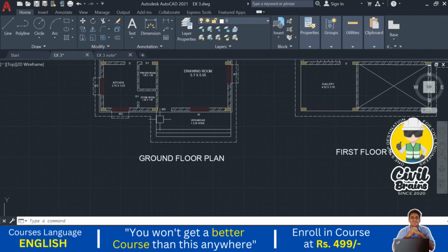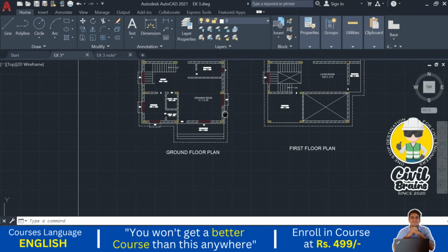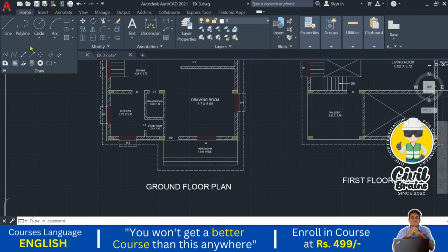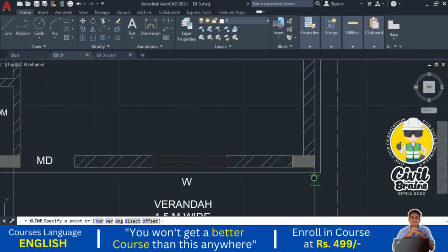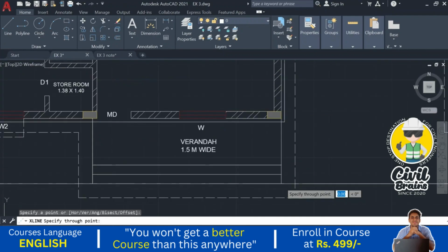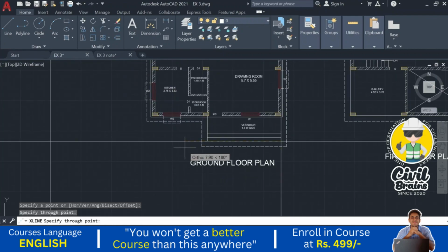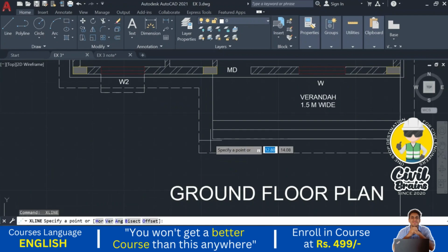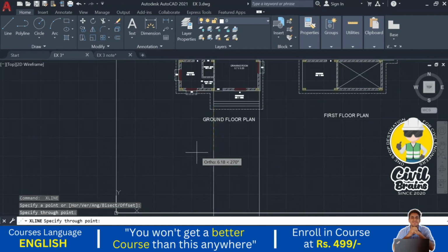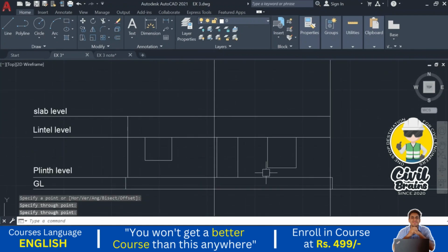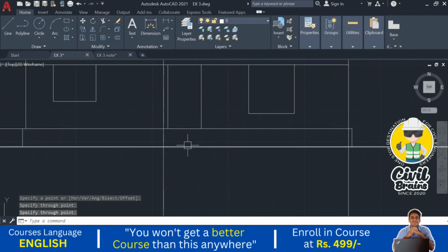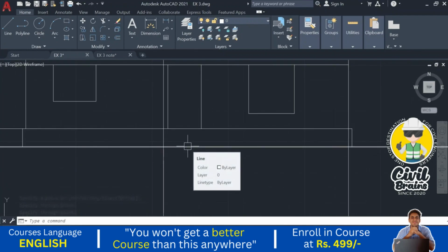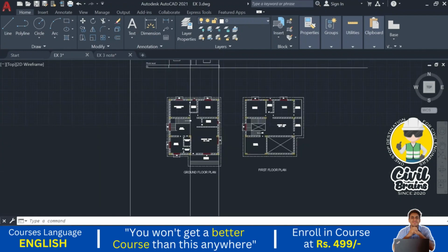So in the front side, this veranda and the steps, correct? So I just extend these steps on the veranda. So this is our steps projection. I just enter here and repeat the same command, press enter. So where will our steps come? The steps will come from the ground level to the plinth level. Only the steps will be there.